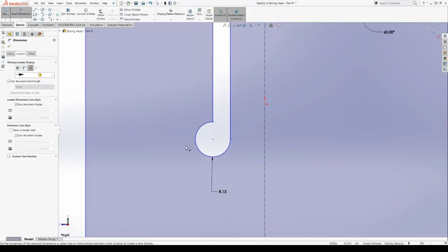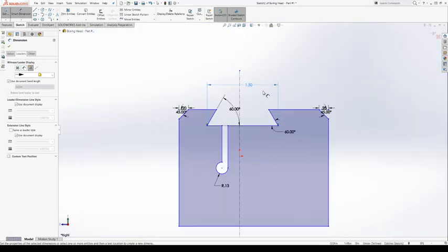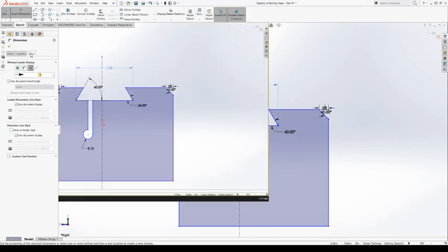So right now we are up with this 1.5 inch dimension. If I wanted those arrows on the outside of those extension lines, I could click on that. If I want them on the inside, I could click on that. This is an automatic, so this is kind of like the smart dimension. It'll figure out where it should be based on what's going on. I can change my extension line style, my leader style. I can change all this stuff, right?